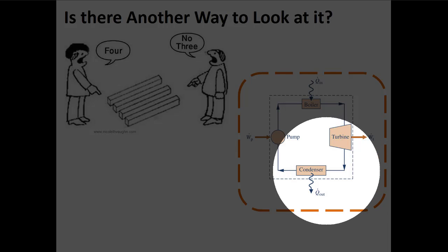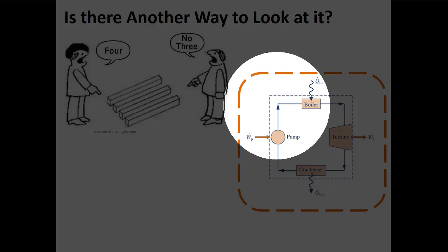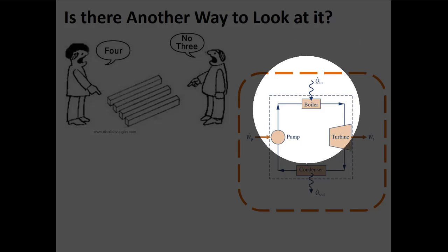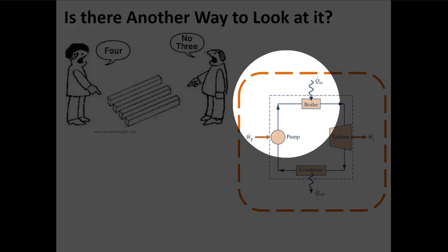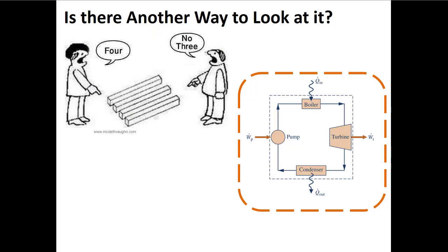So we remove some heat and that vapor cools down into a liquid. Then we run that liquid through a pump to get the pressure back up. So now it's high pressure, but it's liquid and I want steam. So now this is the part where we maybe have to boil, or we have to burn some fossil fuel to add some heat, right? Or maybe we run a nuclear reaction. And that boils that liquid so that we get this high enthalpy steam again to go through the turbine.